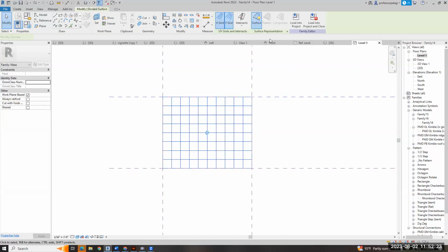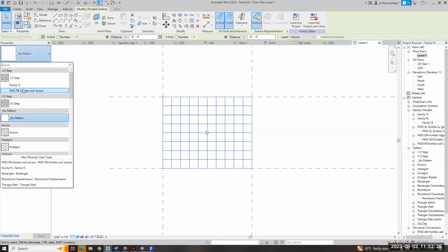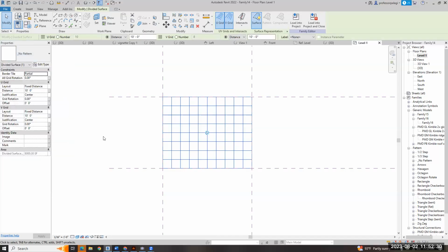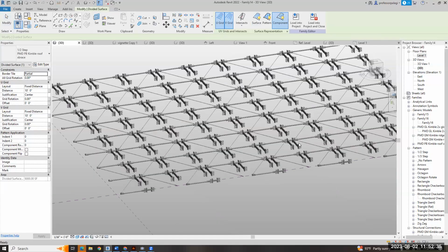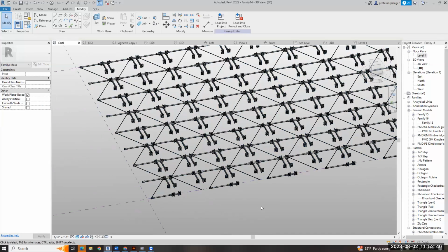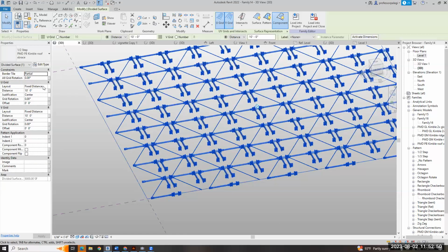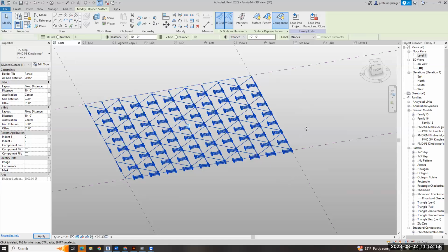Now I could grab that, and I loaded this in already, so I could actually just go, hey, there's my roof X bracing. Okay. So that's the bonus of using the pattern base. It's already there like that. Now I want to be able to snap those beams in also. Oop, these are going the wrong way. I need to rotate. Rotate grid 90. It'll make sense. Yeah. Okay. They're going the right way.